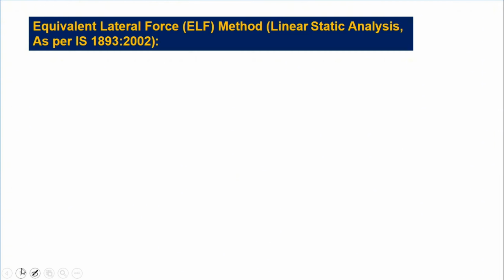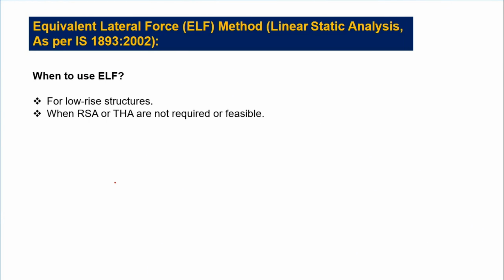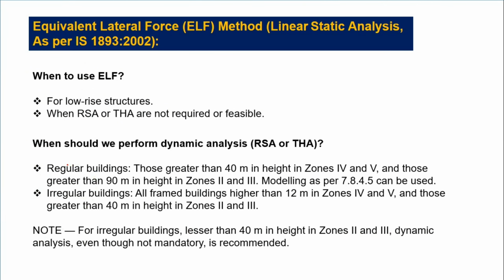This is one of the linear static analysis procedures, and this is mostly used for low-rise structures and when dynamic analysis is not required. We have to carry out dynamic analysis under these two conditions, and if these are not met, then only the equivalent lateral force method will be enough for the design of structures.